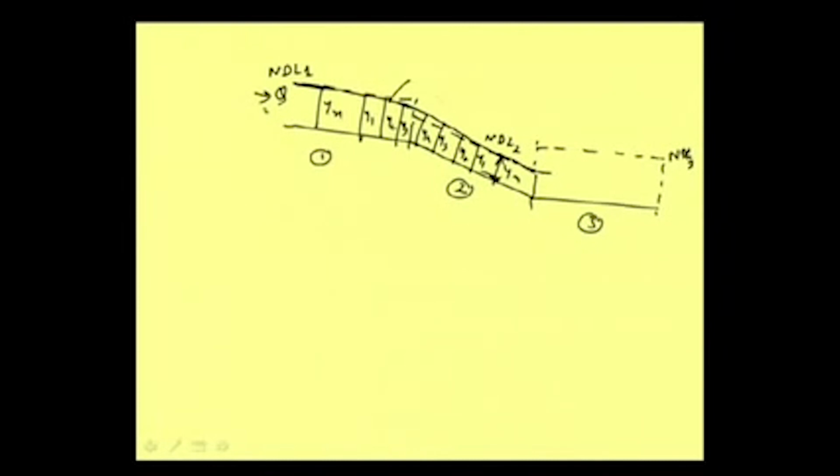But all these parts are gradually varied flow, and when we talk about different types of gradually varied flow, then this part will be one GVF, this part will be another gradually varied flow. This is a drawdown curve, this is also a drawdown curve, but the name of this gradually varied flow profile and the name of that gradually varied flow profile may be different. But right now we just need to know that a gradually varied flow profile can form on the water surface in a channel due to a change in slope. Okay. This is one example.